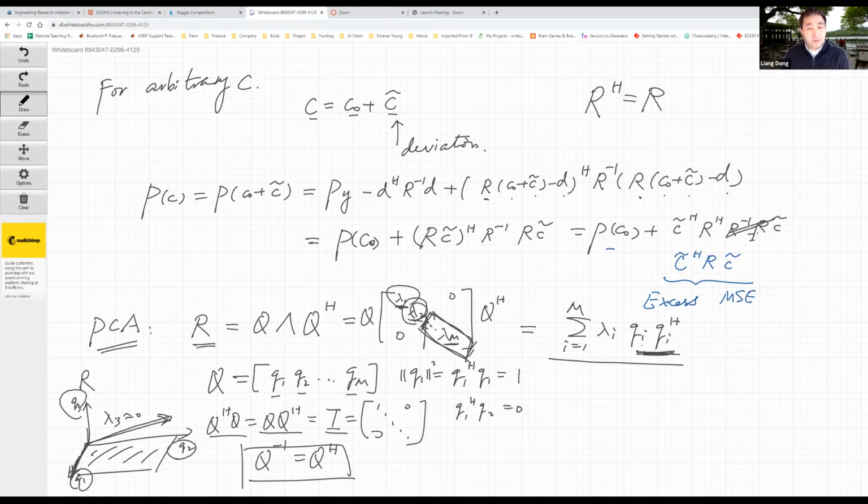So you have some non-zero lambdas, lambda 4 to lambda 10 in my example. That's a very good way to remove the noise, because those are the noise subspace, right? All we need to do is an Eigen decomposition, and then I simply neglect those smaller ones.